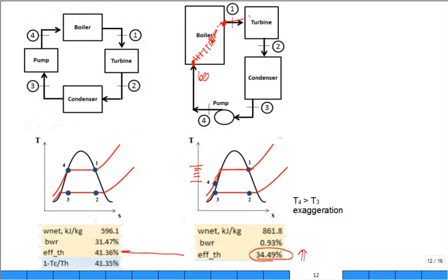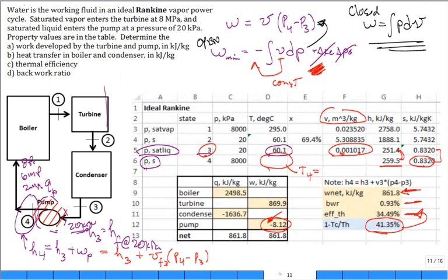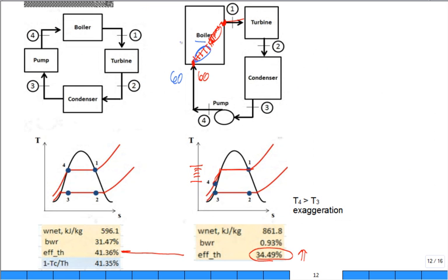Now I'm out. So for the Carnot cycle, all of the heat had to be brought in at TH. Are we bringing in all of that heat into the working fluid at TH? Nope. We modified the cycle. Now we're bringing in a significant amount at a temperature a lot less than TH, between, let's say, 60 and, what was that temperature? I should remember it. 295, 300. So it goes to 295. And then we still bring in a lot of heat to go from 295 saturated liquid to saturated vapor. And right there is the Achilles heel.